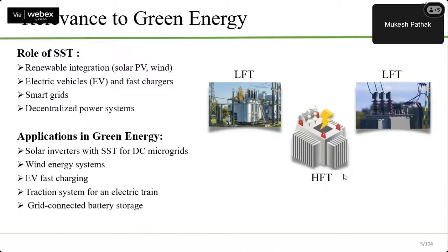So if there is a step of 10 volt and there is a 5 volt fall, then this tap changing arrangement will give you an additional 10 volt jump, which will be more than the fall in voltage, which is 5 volt. So you will get 5 volt more.